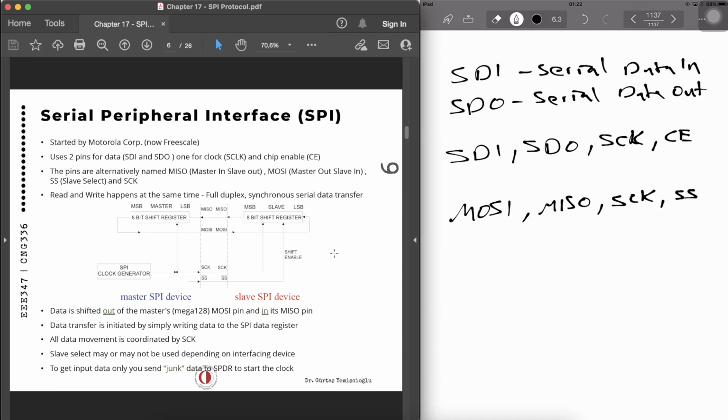And there's also a widely used standard, which we call the 3-wire interface bus. In the 3-wire interface bus, there are only SCK, chip enable, and a single pin for the data transfer. And the 4-wire bus can become a 3-wire interface when the SDI and SDO data pins are tied together.